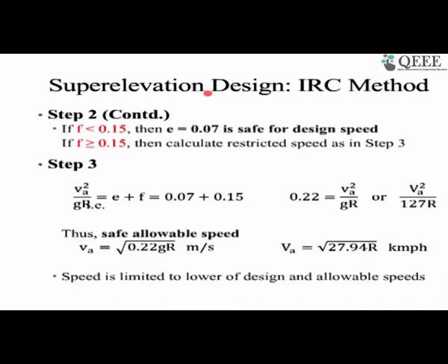The second part is that it's very easy to maintain the profile of the pavement. Recently we received a query from the industry. They constructed an airport concrete pavement, and they found that the level was wrong, and in some places there was water stagnation. Now how to repair this? This becomes a headache. If it was a bituminous pavement, they could easily overlay it and make the level. So definitely there are a lot of other issues like this.